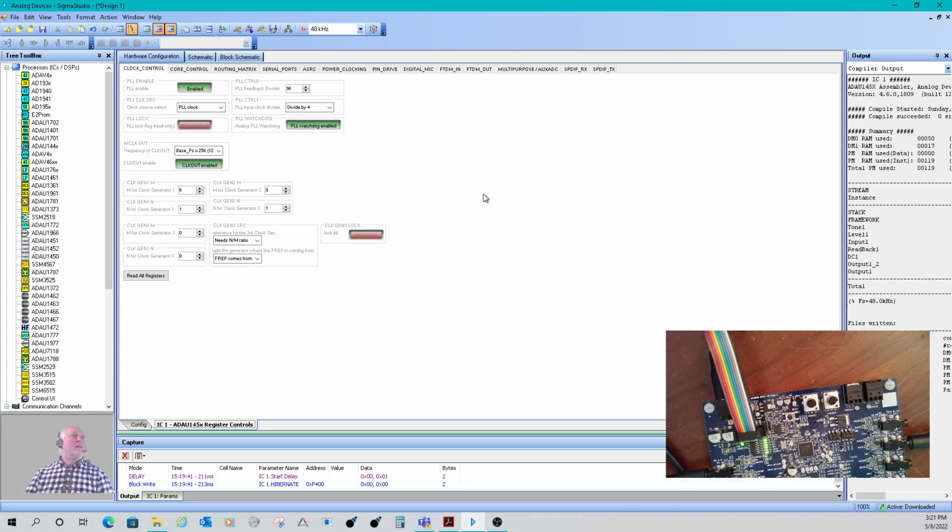So to set up the sample rate correctly, the third piece of this is what clocks you are sending. You could have 48K set up in the compiler, and 48K set up in the register settings, and then send it an oscillator that's half the rate.